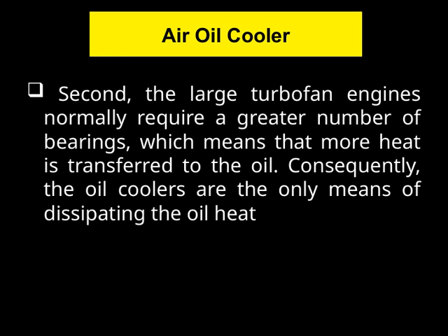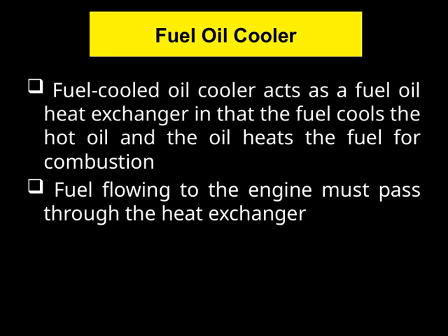Now let's take a closer look at the fuel-cooled oil cooler. Essentially, it functions as a fuel oil heat exchanger. What this means is that the fuel helps cool the hot oil, but at the same time, the oil heats the fuel, which is necessary for combustion. This reciprocal heating and cooling process is a key part of maintaining optimal engine temperature and efficiency.